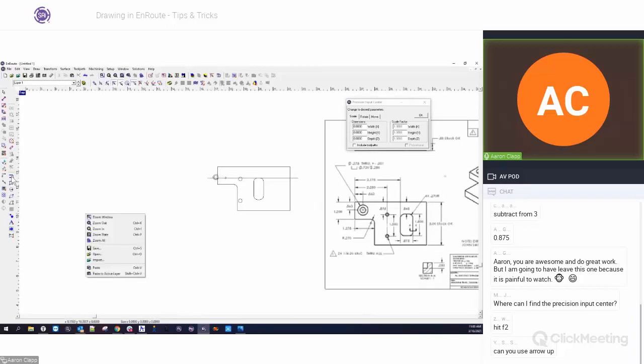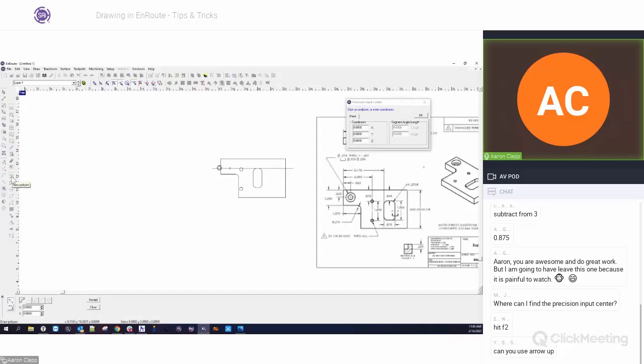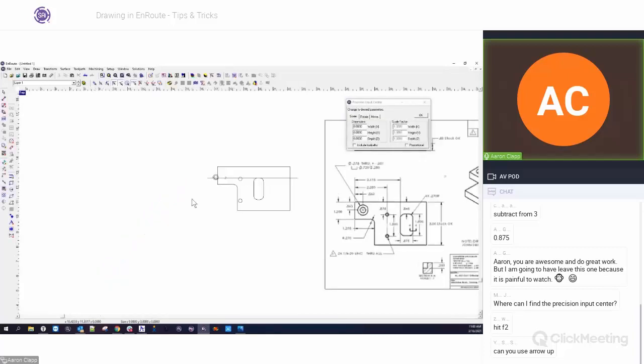You can also create freehand drawings. If we go to our poly arc drawing tool and I click on create an arc, I can set my specific point. I'm going to go ahead and just snap to a point here somewhere on screen. And now I get all these different options as well. I can set a direction, I can set my arc center, I can set my arc radius, and I can also set a sweep angle. So I can do all kinds of things in creating different types of arcs right in here. If you're doing this by hand, that's really good.